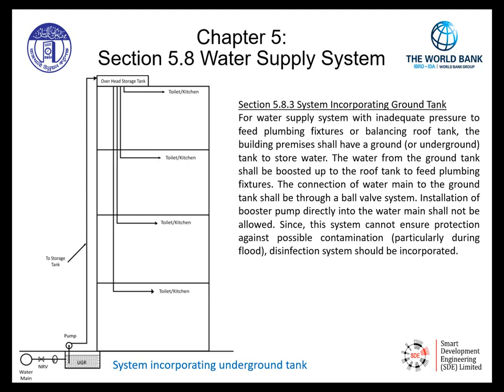The connection of the water main to the ground tank shall be through a ball valve system. Installation of booster pump directly into the water main shall not be allowed. In other words, we are allowed to have the pump above the underground reservoir as shown.